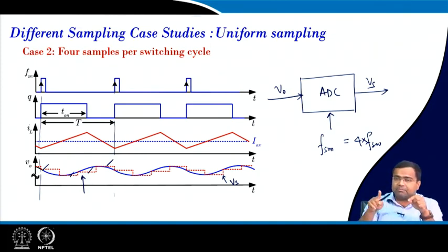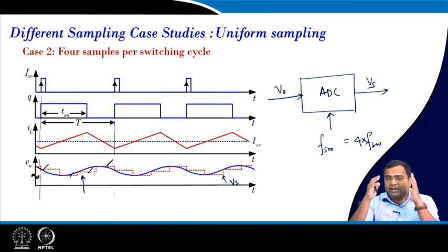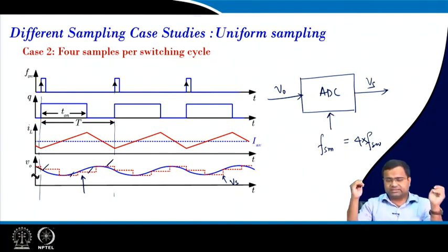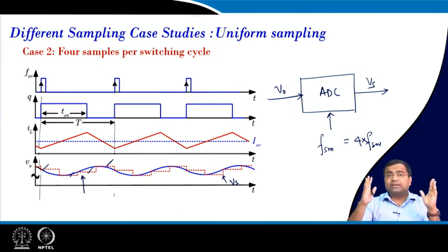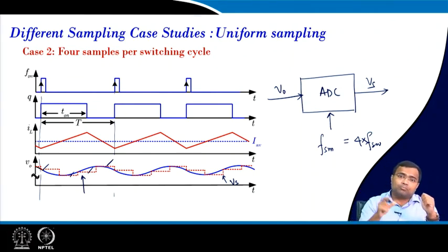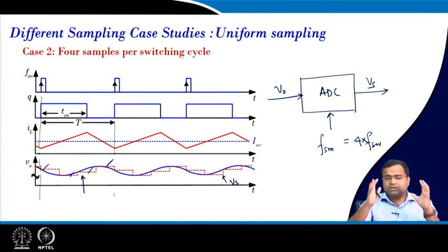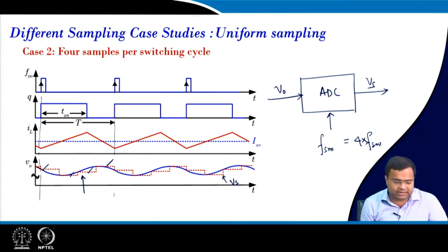So, if it is a fixed number, and if there is no change in the output voltage, and if there is no change in the controller output, then I can say, why should I sample? So, I can just keep watching the digital ADC, and I may not sample at all, it will behave like an open loop system. So, in that case, we can reduce the sampling rate just to save power. That means, we are taking the sample, but we are not computing the digital controller, we are just keeping it idle and holding the value. So, there are many possibilities that we can discuss.